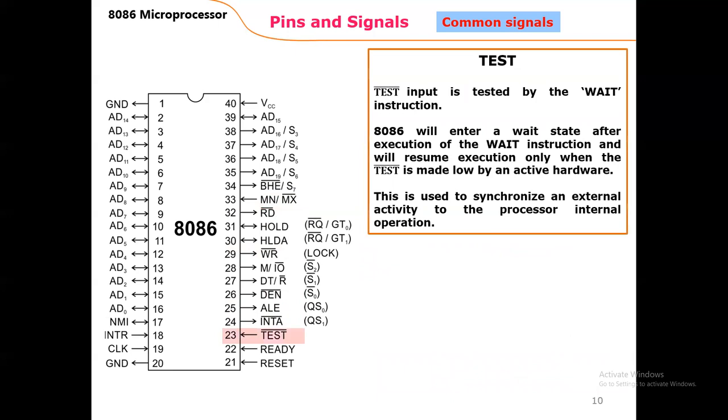Next, TEST. This pin is an input pin, and it is tested by the WAIT instruction. Your microprocessor will enter a wait state after the generation of the WAIT instruction, and it will resume execution only when the TEST pin is made low by active hardware.